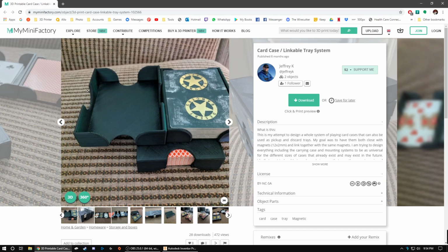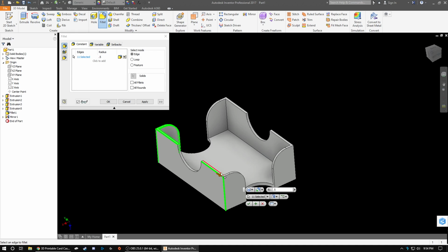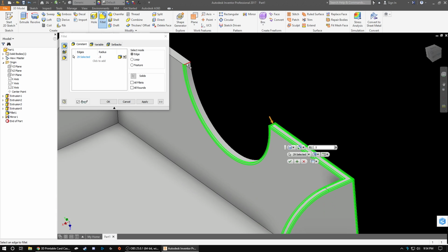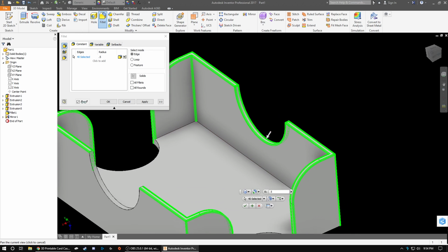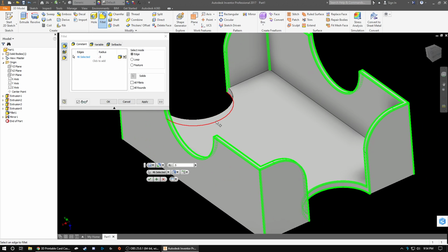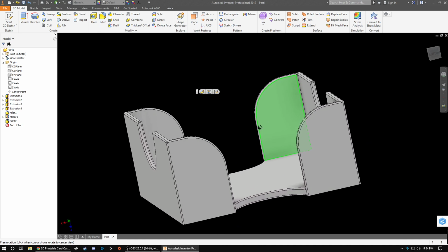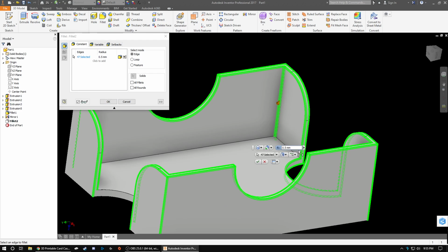Now in this, there looks like there's some nice radius edges all around. We already know how to use the fillet command. We could give it some nice small little 0.5 millimeter radius edges, just making nice soft edges so you don't hurt your fingers. If you're 3D printing this, then yeah, you want to add little things like this because it'll actually print it out. It does add to the complexity of the print. If you're just drawing this to get geometry for laying things out, you don't need to put the radius edges in there unless it's important. But now that gives nice soft edges in there. And again, if you wanted to add more fillets to it in that same feature, you can either right click edit feature or double click and click here, and you can keep on adding them.